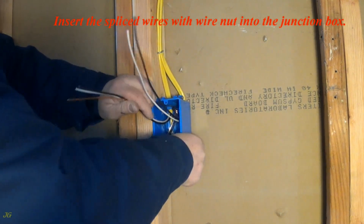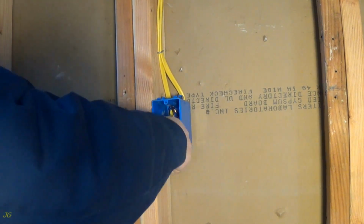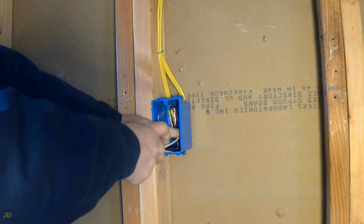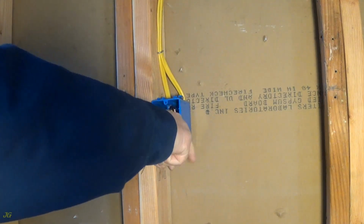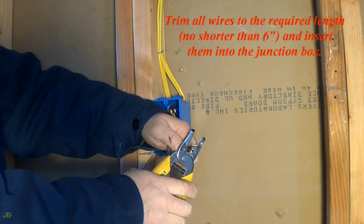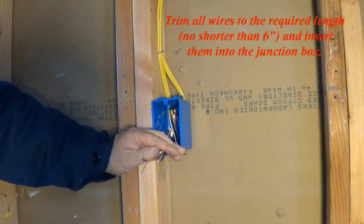Insert the spliced wires with wire nut into the junction box. Trim all wires to the required length, no shorter than 6 inches, and insert them into the junction box.